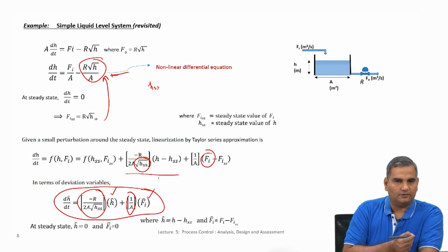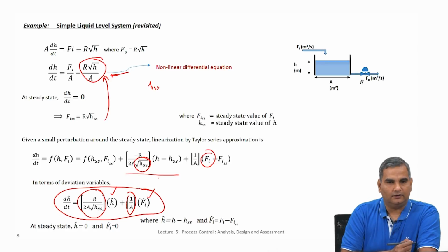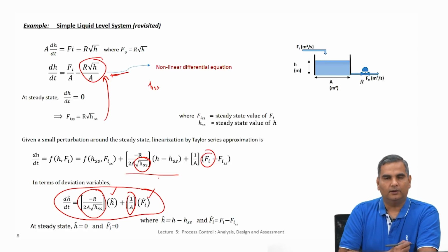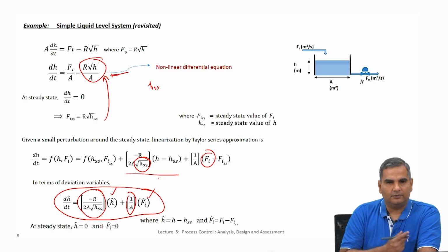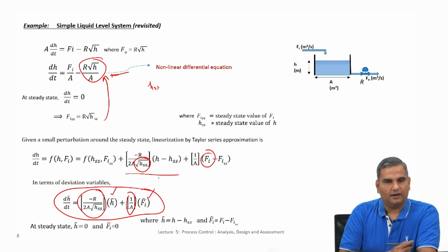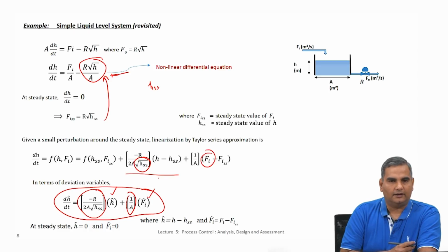So, in this lecture we looked at process modeling: how it is a question of defining the correct process variables of interest, defining parameters of interest, and then writing the conservation equations and the phenomenological models. Make sure that you have enough equations and variables, and that you write these conservation equations for control volumes.